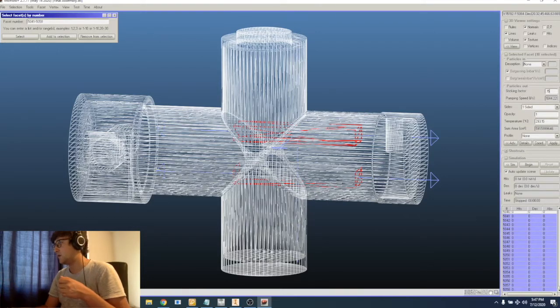These are 1,400 liters per second each for hydrogen, but that was measured at 10 to the minus 6 millibar. Ultra high vacuum is 10 to the minus 11 millibar, so in reality the pumping speed is probably going to be a lot less. Here the pumping speed calculated based on the sticking factor is 1,000.